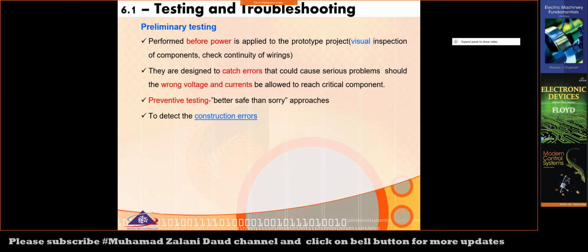Okay, for example, this is our prototype. In the preliminary testing, basically what we do is just to observe: is there any wrong connection, is there any wrong placement of the component, right? Is there any loose wire, for example? Okay, so we check the continuity of the wiring. For example, we can do the continuity check using the multimeter, which is something that I've shown you before.